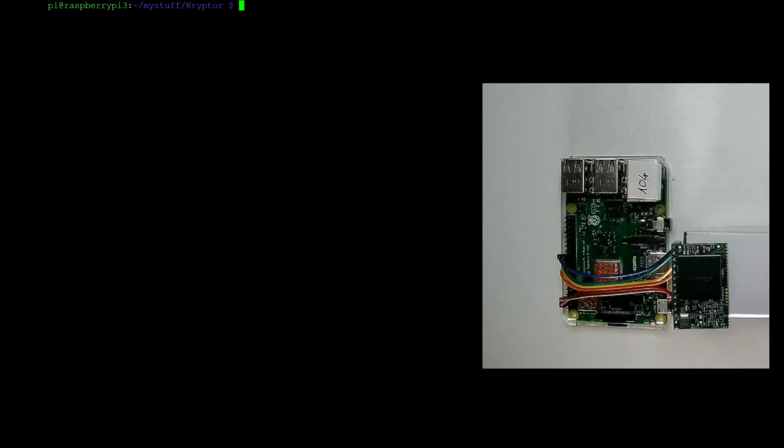So the problem, to simplify it, is that the quality of these random numbers is actually very difficult to achieve on a software basis. So you don't really have a true random source of entropy or pure chaos to trigger and generate purely random numbers. That's why in software you usually have this pseudo, while when having a hardware component, a hardware generator, you can reach what is called a true random number generator, a TRNG.